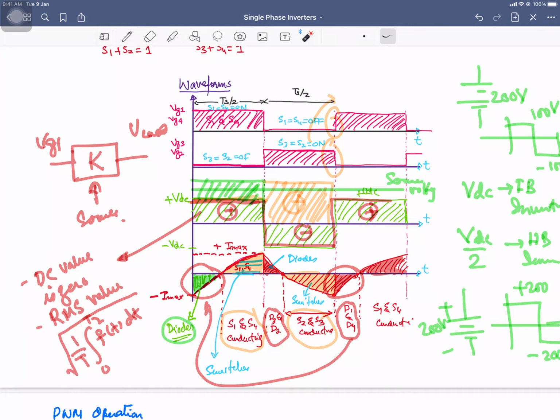So the RMS value, root mean square value, gives you the effective DC, you can say, in the AC circuit. But in terms of average value, that is going to be 0 for the load voltage waveform, because positive and negative areas are equal. So source voltage is constant, load voltage is changing its polarity, and the RMS value exists, right?